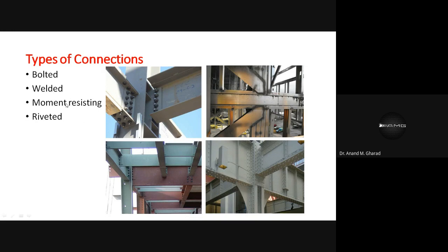The major value will be governed by the moment, and the secondary value is of shear. So in mostly the frame connections, you will find that the moment is predominant, and that moment at the joint or at the ends, that is at these locations, has to be resisted.